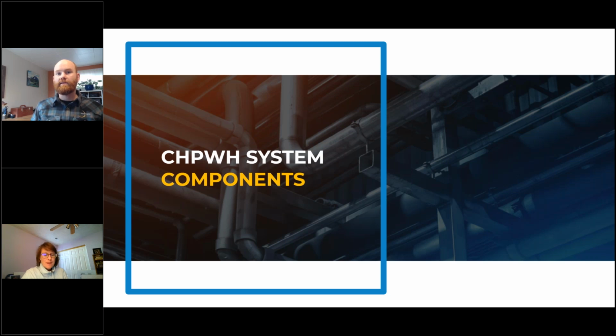Yeah, so if you're working with a manufacturer that's providing a skid, you're going to want to ask them, what is the refrigerant that the heat pumps are utilizing in the skid, and what are the ambient air conditions that I can run that heat pump in? Understanding that first will help you understand whether you can put this on a rooftop or maybe you want to locate it somewhere else where you have warmer climate conditions, or maybe you want to move to a different type of heat pump that uses a different type of refrigerant that can handle your local climate conditions.